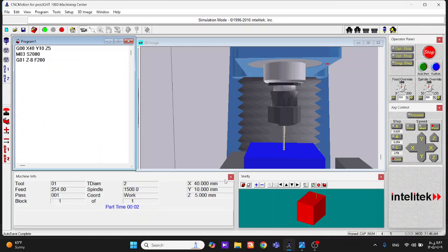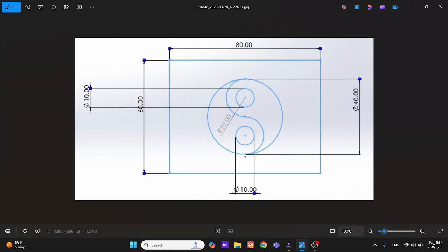By the way, now I need to move from here counterclockwise to this point. When I'm moving from this point to this point, is my x going to change? No, x is the same position. The only thing that will change is y. Y is here, it was 10. When it goes here, it should be how much? Because the whole circle is 40 and we are at 10 here, 10 plus 40, it will be 50. So I should write G01 linear interpolation.